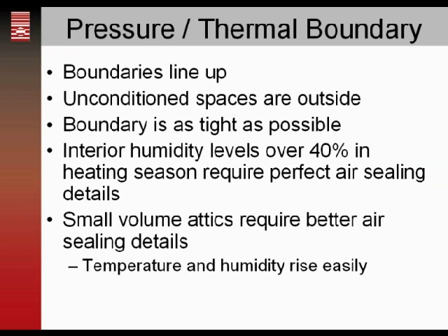So we want our pressure boundaries and thermal boundaries to line up, and we can tell if they are by the pressure numbers we're reading. We want our conditioned spaces to be outside, close to temperature and relative humidity as outdoors. We want to make that boundary as tight as possible. That's the goal here. We want to make that boundary as tight as possible so the insulation we have is effective, so the air isn't getting right past the insulation and causing problems.